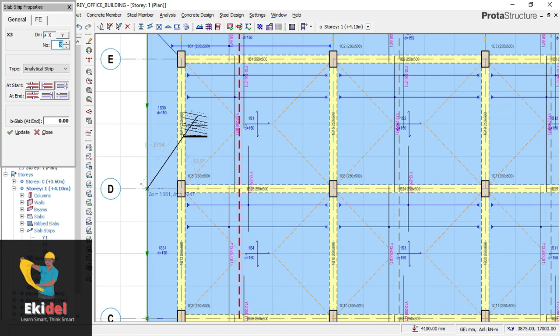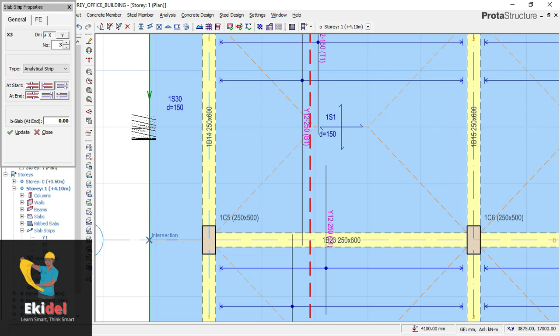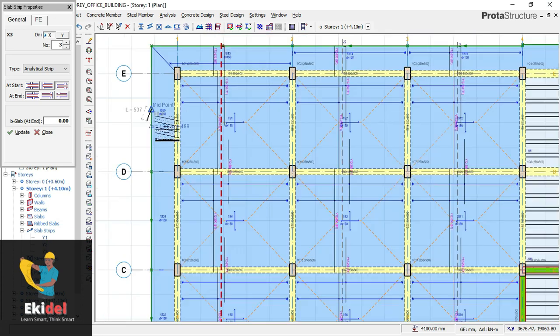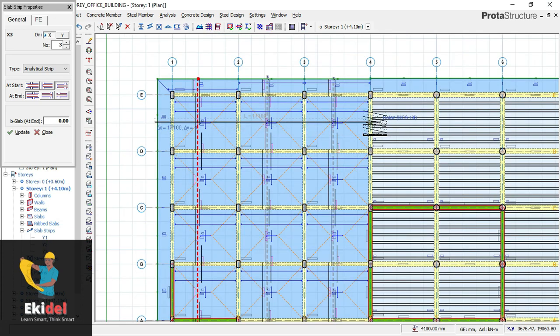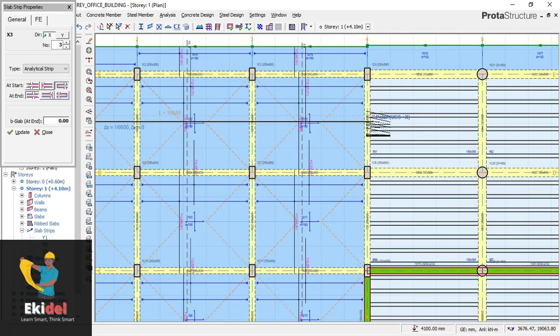very point, no, not this very point, escape. You have to locate it very well to click. So I'll click at this very point right now, not really, it's trying to snap to that very point, so I'll click somewhere here and then go all the way down, holding my control key, and then click just after this place, because I've already chosen that this ending point will be that there is a slab at this very point. So I will now click here.